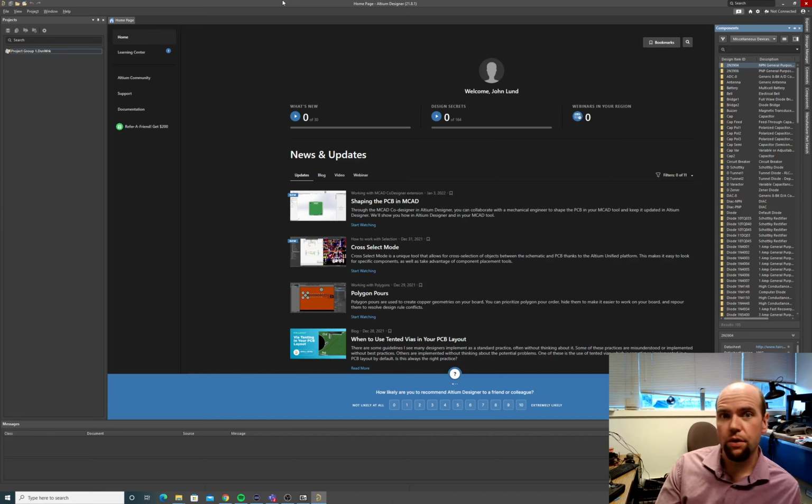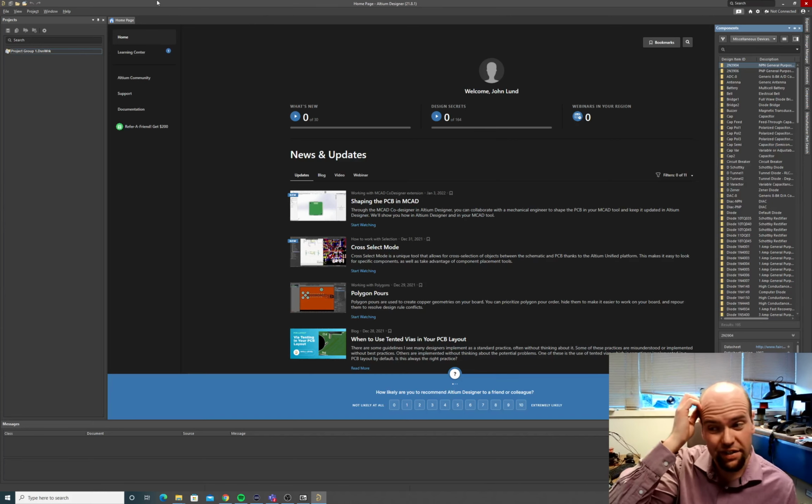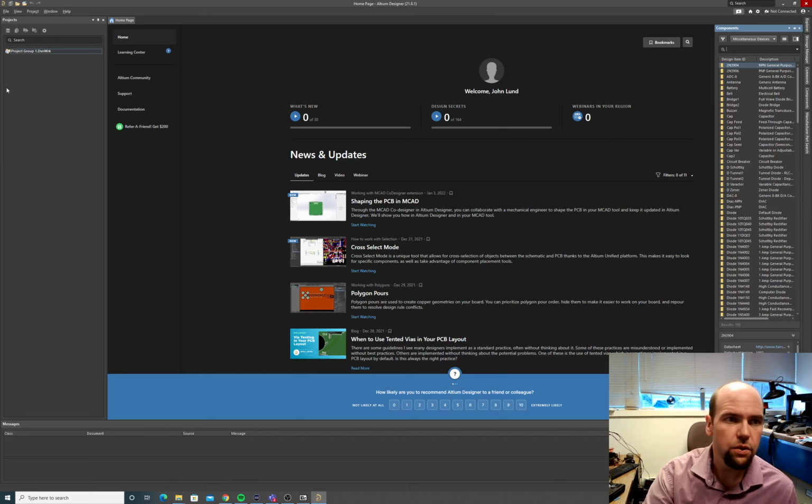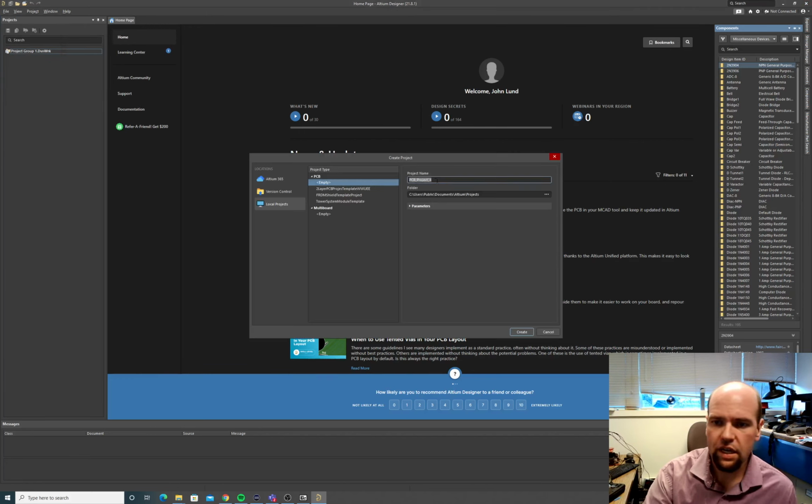And so you have multiple components on one single circuit board. To get started, we're just in Altium here. It's already open. The process of loading, installing, and exporting is all going to be in separate videos. This one's just about putting multiple components in a useful format on a board. So we're first going to create a new project, and I'm going to call this Proto pieces, and we're going to use the 2-layer PCB project template.